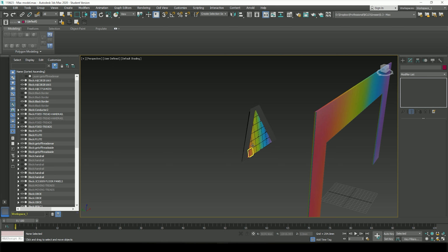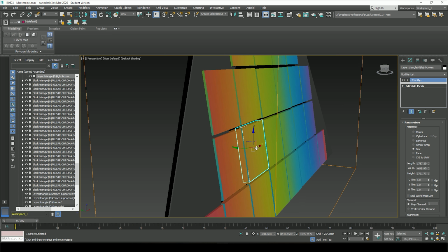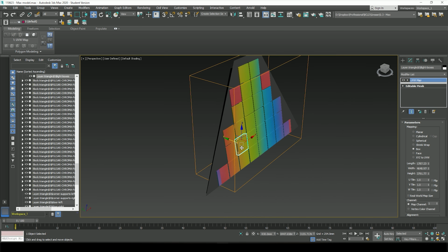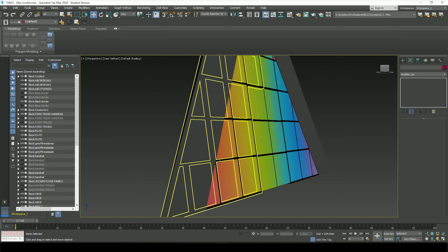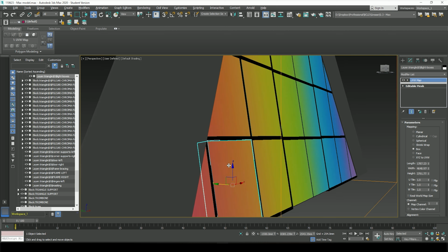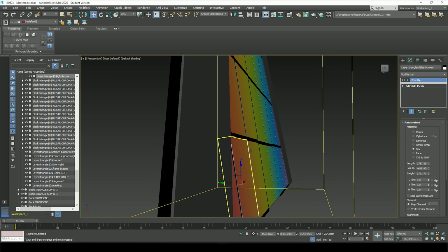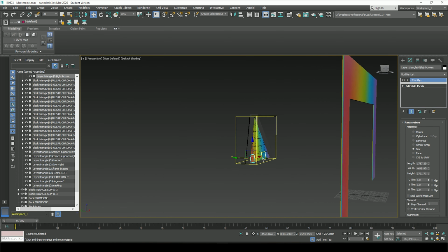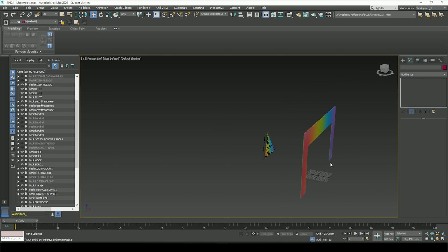If you're interested in what this moiré effect is, what that means is that there's two objects sitting right on top of each other. So if I drag that out, you see now it doesn't do it so much. Oh no, it is. There's two planes sitting right on top of each other, which you fix by making sure that they're not sitting on top. It's just lots of objects all right next to each other there, all interacting with each other, intersecting. And that happens quite a lot with CAD drawings that have been imported into 3D Max, and you can fix it by making it yourself in 3D Max and just having nice efficient modelling, which I'm not going to cover here, as I keep saying. We're going to do that in a completely different series. I'm going to go into a nice deep dive of 3D Max because it's such a great tool.